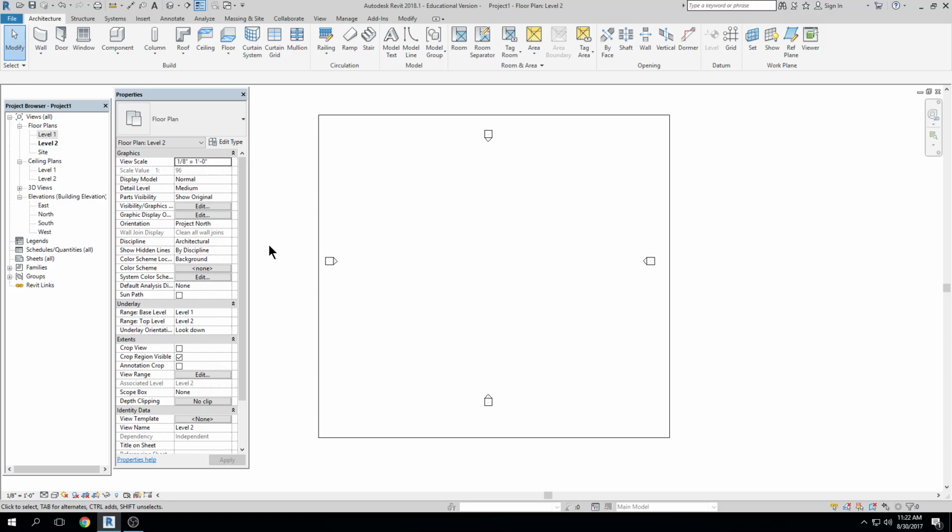In AutoCAD, it's very easy. You click, click, click, click away, right? It's really simple to make lines. In Revit, we're not drawing lines, we're drawing objects. Okay, so there's a difference there. We're drawing objects. And in this case, we'll be drawing walls. All right. And again, this is very simply how to just draw them, not how to define them. So we'll talk about that a little bit later.